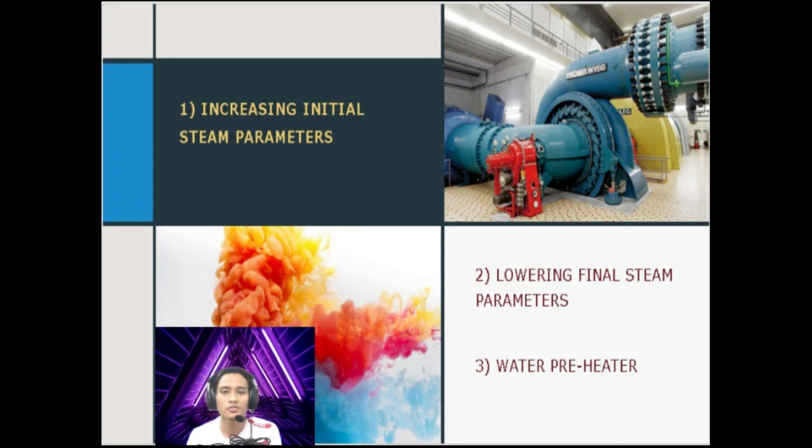Furthermore, the extraction consists of several stages, where the longer the extraction from the turbine takes, the lower the temperature of the water for heating. In this way, steam could do more work in the turbine before getting extracted, thus increasing the thermal efficiency of the turbine. Each turbine has a distinct set of optimal steam extraction parameters. Theoretically, the more stages involved in the steam extraction inside the power plant, the higher the total efficiency of the power plant would be.